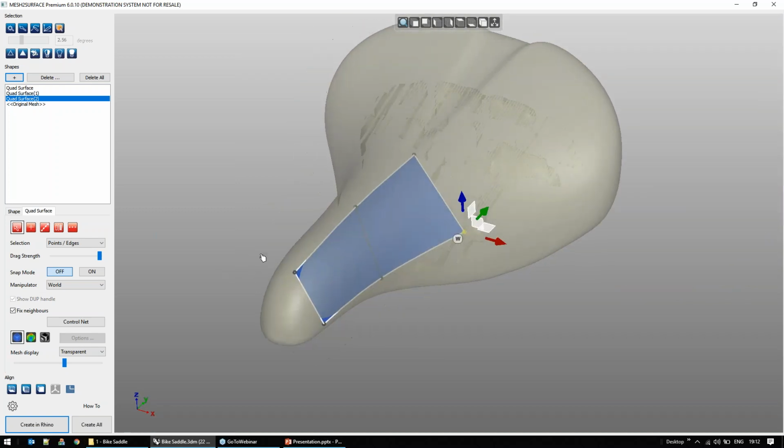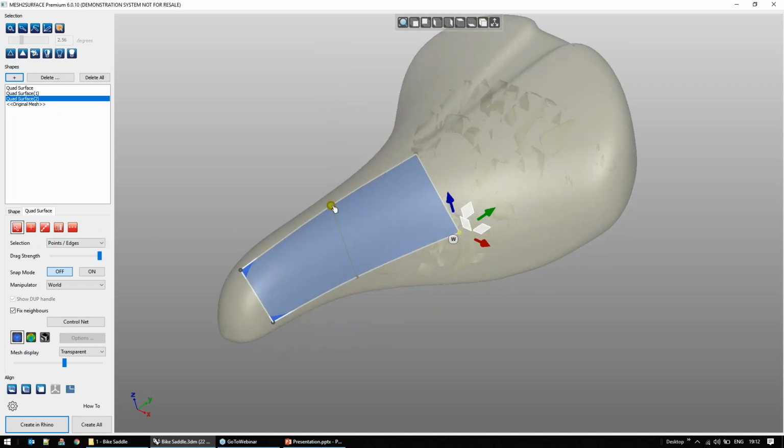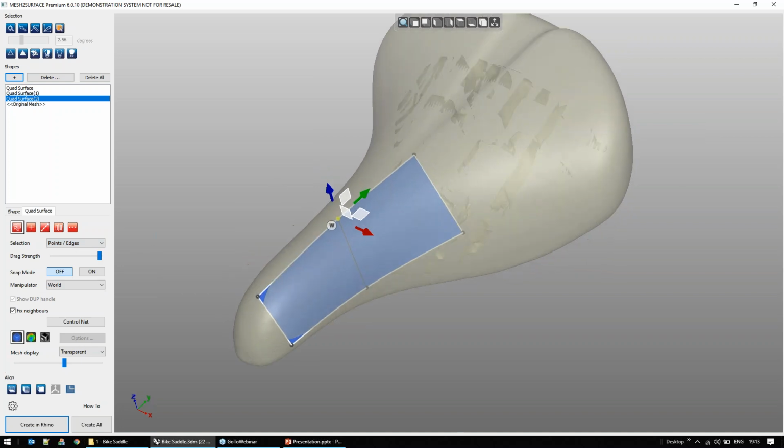Also, when you want to navigate these objects, you can choose how you want to play with the faces. You can choose to select only points, only edges, or any point, edge, and face. In our software, we have something which is called pointed edges. I personally find that this is quite convenient and easy to use, so this is my favorite option.